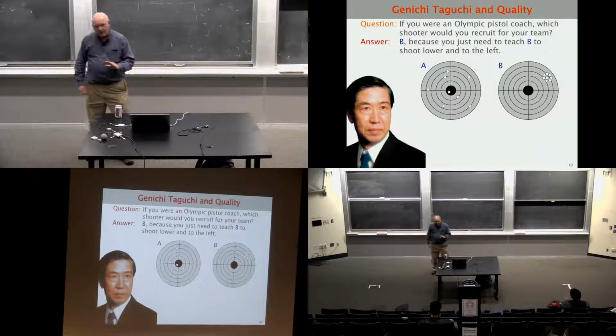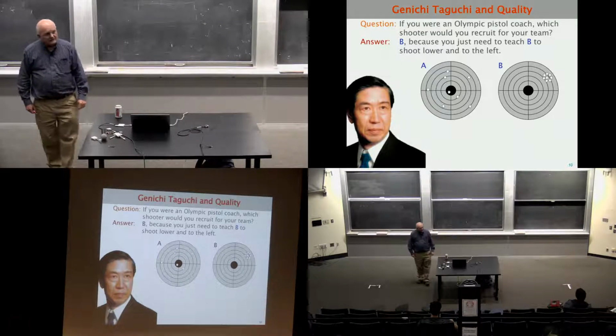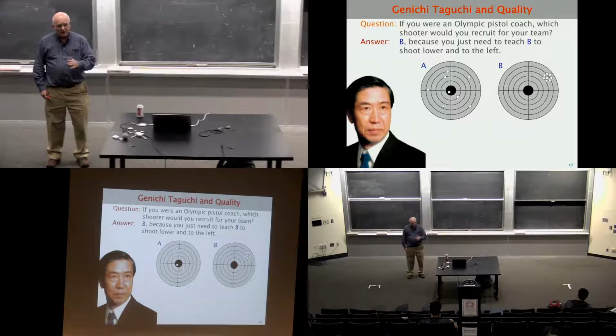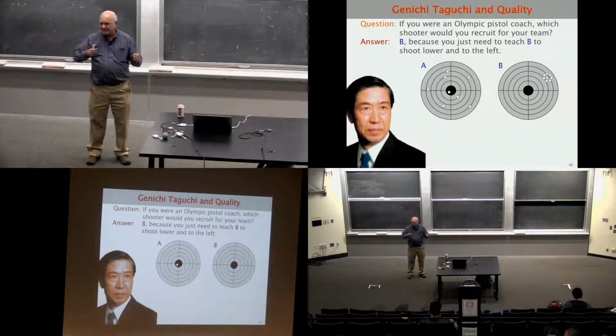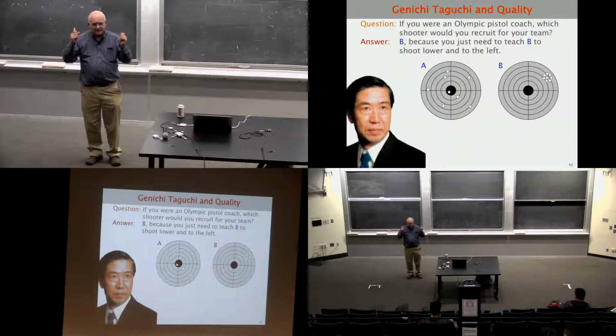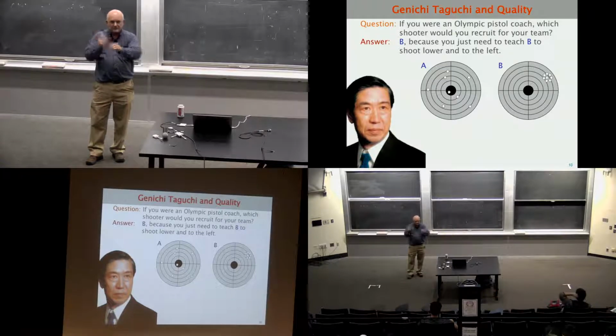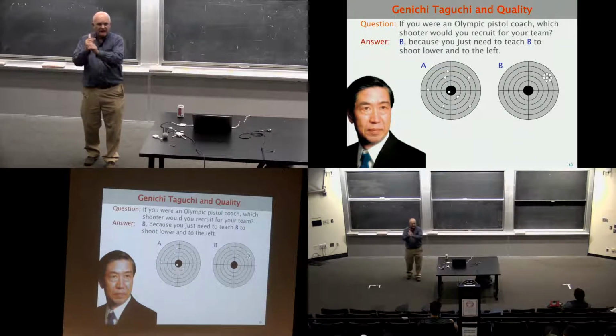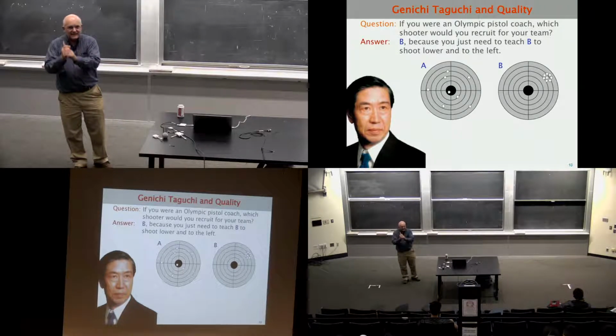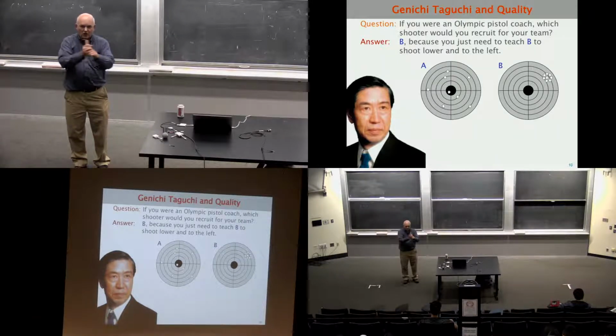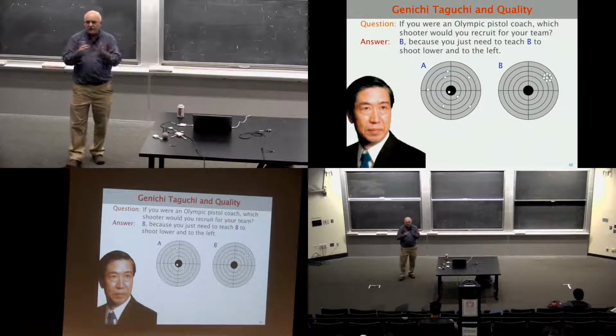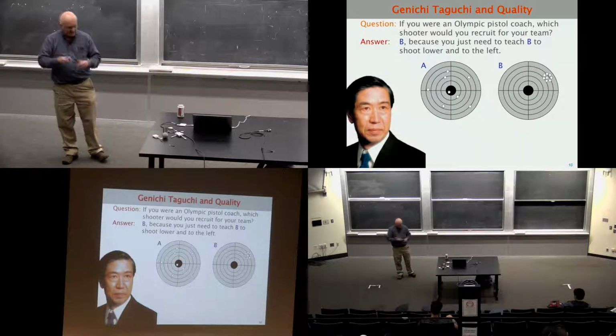And so what he did in the realm of quality control was say, look, when we're producing products, before we try to fix the reliability or increase the quality of the product, let's first reliably produce whatever we're producing so we get the same thing every time. Because then we can go in and see what the problem is and adjust for it. So the idea is to go after the variance first, go after the spread. Try to get the spread as small as possible. Try to figure out how to isolate and produce the same thing, even if it's not very good, and then try to make changes. Because if you try to make changes while you have high variance, you don't even know if you're making progress or not. It could be in the noise of your measurements.